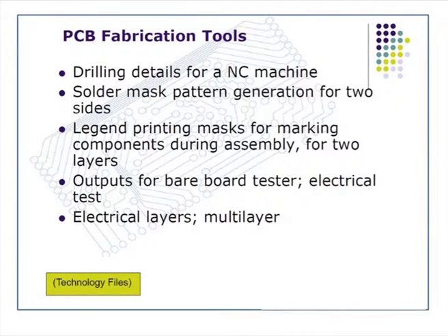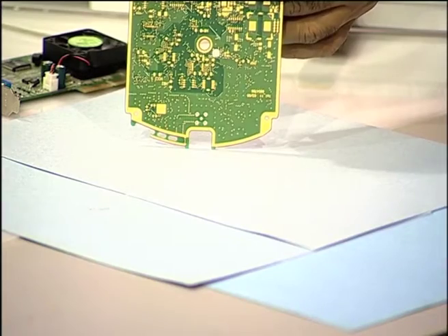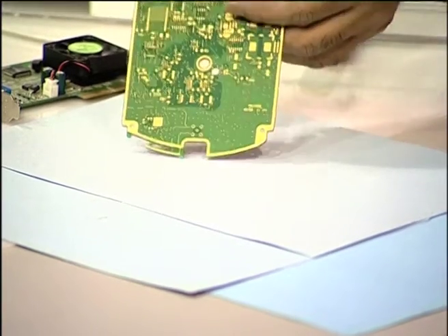Now, the output of this activity that we have seen so far, the activity that I have listed so far, right from schematic to simulation to the layout design tool, will be to create outputs for drilling, because as you know, if you look at this board here, there are a number of holes which will interconnect components.